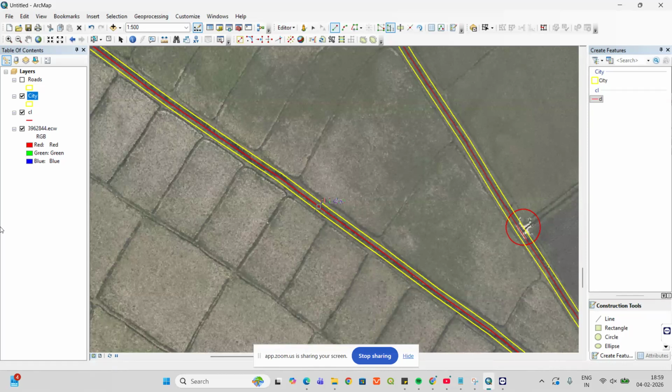So in that case, we'll perform these flights at a very low altitude. Since it is all hilly terrain, if you fly at a greater height, you will not be able to see what is beneath the ground level or beneath the trees. So we'll perform it at around 60 to 70 meters with a terrain sensor also. Our drone data will not be matched with the elevation data, it will be matched in relation to the ground level. So when the ground level is 200 meters, my flying height will be 250 meters. When the ground level is 210 meters, my flying height will be 260 meters. So the data I am getting will be evenly 60 meters from the ground level.